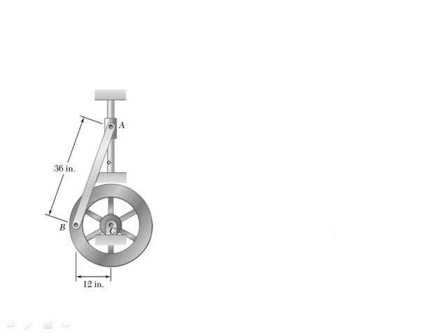Now keep in mind it's going to be down here in this position in that final scenario. So here's A, and here's B. And let's give the flywheel some omega. I don't know what it is, but I'll just call it omega F. And it's in the negative k direction, it's clockwise. And I can see that the wheel is going to be moving in this direction at its base. So the velocity of B with respect to C is going to equal minus 1 foot times omega of the flywheel in the i hat direction.